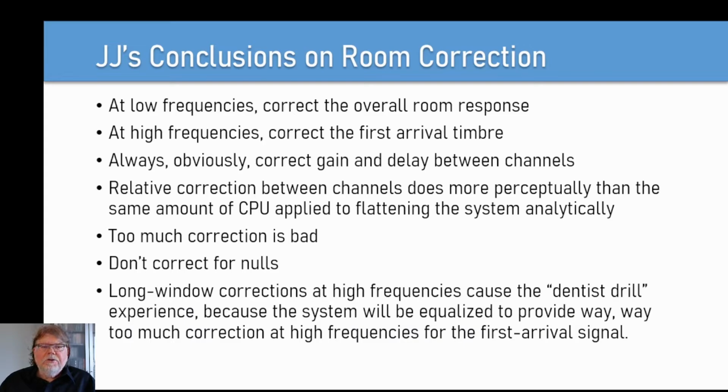The conclusion on room correction from JJ's slide presentation is that at low frequencies, we want to correct the overall room response. At high frequencies, we only want to correct the first arrival timbre. Always, obviously, we should correct the gain and delay between channels. The relative correction between channels does more perceptually than the same amount of CPU applied to flattening the system analytically.